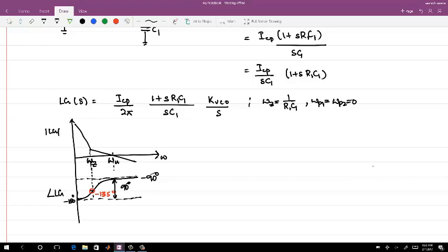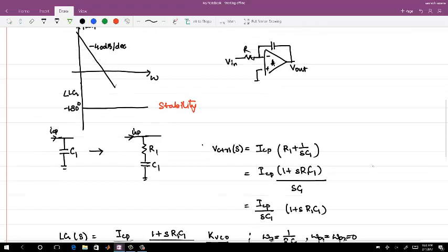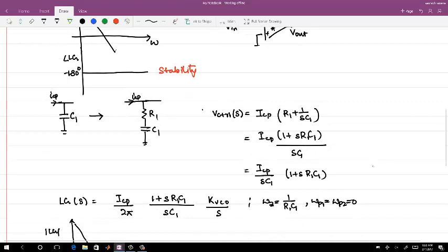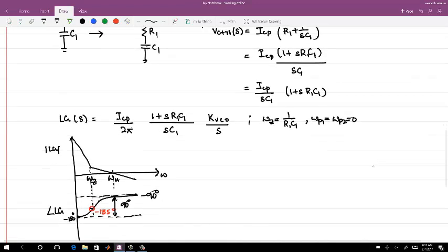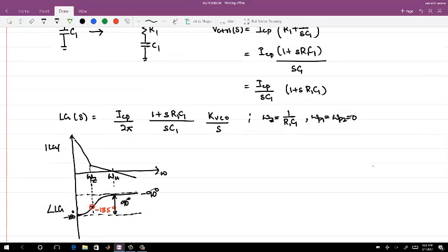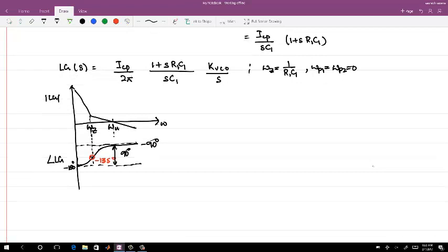Any questions? So far you have seen that I started with one integrator, and then I added a proportional path for stability reasons, and I am getting a good phase margin. It's a stable system, so I should be happy, and it's all done. And this is the PLL design, right? You get the frequency, you get the phase error.